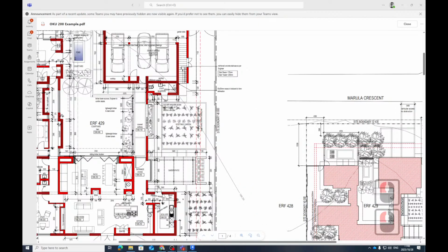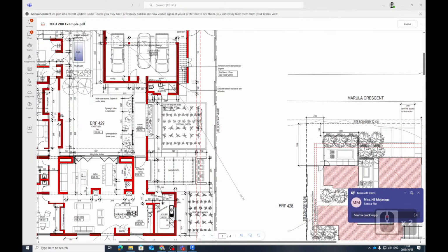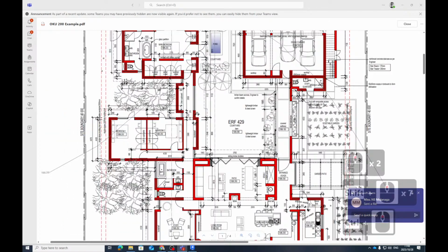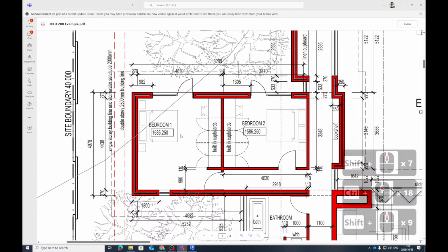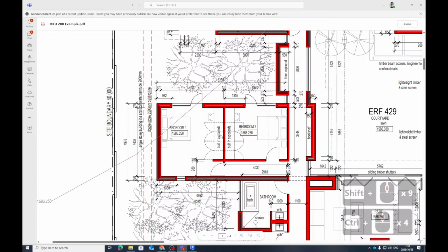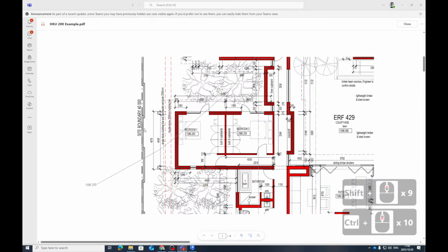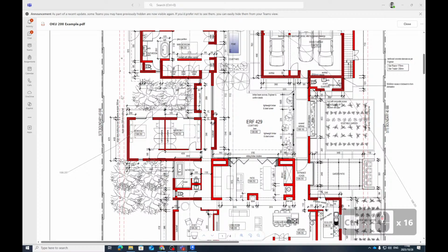If you go and look at how the kitchen counter is shown, it's very little. Yes, we do show some of the furniture, but it's not required. Where you are building in a TV cabinet, then we do show it. Again, where the cupboards are, but the detail is very basic. It's just so that the contractor knows there is a cupboard there and we need that. It's to inform them what we're doing so they have a better idea. But that's all you show. None of the detail. It's very limited. You focus on how the walls are put together and how they are annotated.